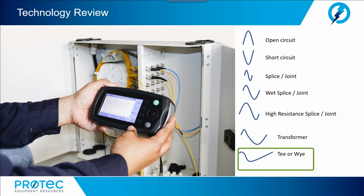Now, also, if we were to have a T-tap or a Y or branch connection, what the TDR would see here is the large capacitive change due to the branch of cable or the section of cable that is being tapped into the main run.